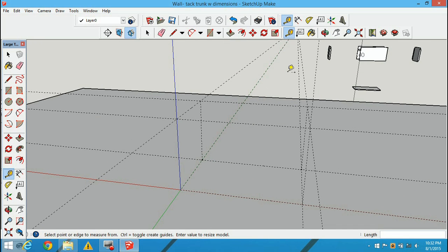A couple ways you can do this. Again, always keep in mind we're starting with a two-dimensional object, and then we're going to work out. Now look, when I click my rectangle tool and I move, notice I clicked in that corner and I moved down. Look at your bottom right hand corner. It's always the question, which dimension comes first? Is it the width or the length? In Google, it'll throw both different arrangements to you. But I can look here. The skinny dimension is the first number. The higher dimension is the second number, the 20 inches that you see there right now.